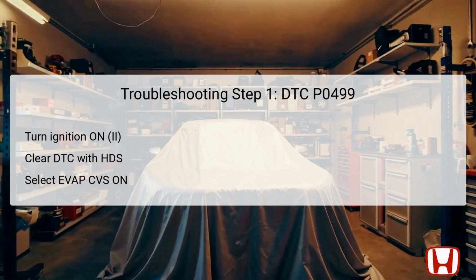The initial step in troubleshooting DTC P0499 involves turning the ignition switch to the ON position without starting the engine. This step powers up the vehicle's electrical systems needed for diagnostic testing. Next, you should clear any existing diagnostic trouble codes, DTCs, with the Honda Diagnostic System, HDS. The HDS is essentially a tool that allows for efficient communication with the vehicle's computer systems.